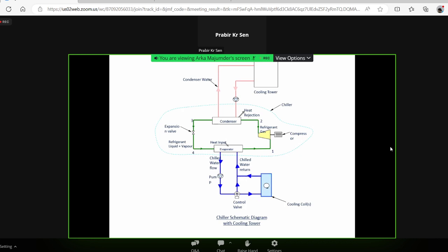The condenser is, again, a shell and tube heat exchanger, where the refrigerant is in the shell and water flows through the tubes inside that shell and tube heat exchanger. Water cools the refrigerant, and it becomes a little warm refrigerant liquid when it comes out from the condenser. But in the process, water gets heated up. So we don't throw out that hot water.